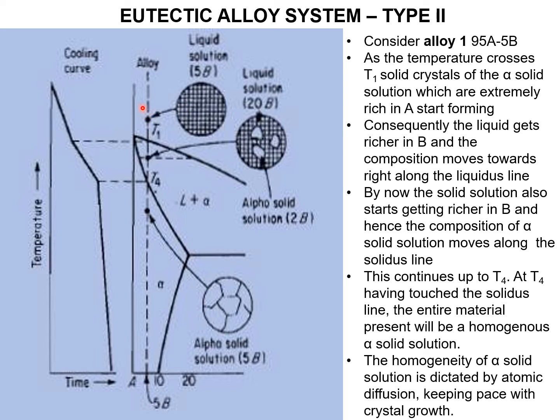Once we lower the temperature, the liquid range becomes less and the solid grains increase because of the diffusion mechanism. From this we want to find the liquid percentage and solid percentage. We can apply the lever arm rule and find the liquid and solid percentages.